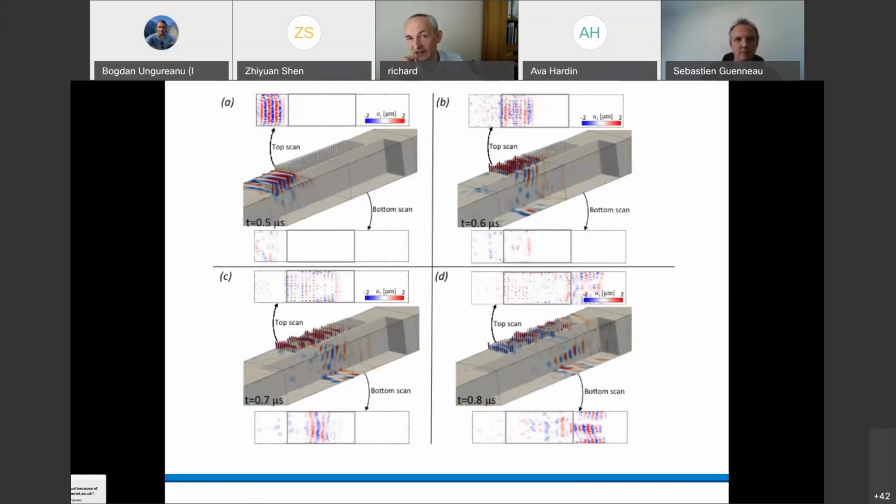It's localized into the array. The array is beginning to shed the shear wave into the bulk. You get the signal on the bottom, and then it excites a Rayleigh wave on the bottom of the sample, which then trundles along. So this is experiment and theory working very nicely together, as we would hope.